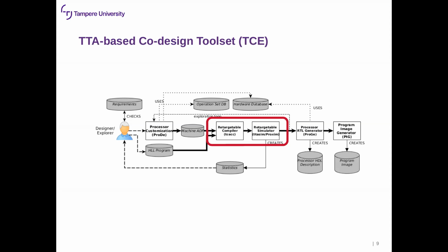And basically, once you're happy with the results, you would then go to the RTL generation phase, where our tool is able to generate all of the operations in our operation set base, along with these extra things for the instruction stream, for example, and also hardware test benches to initialize your simulations.